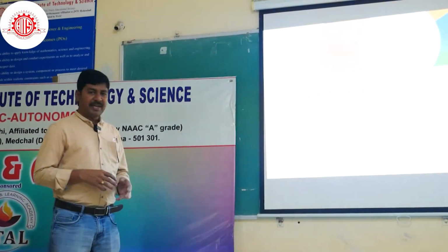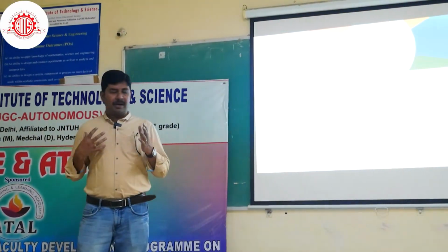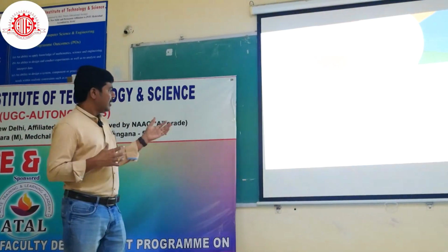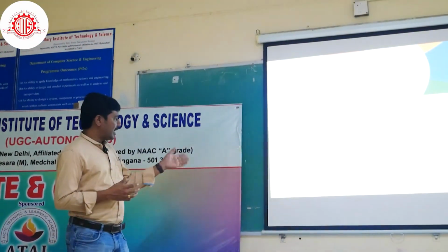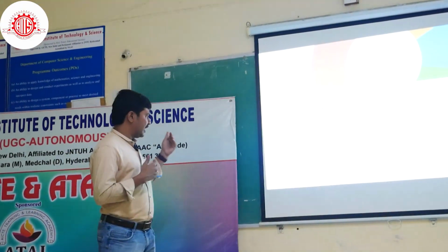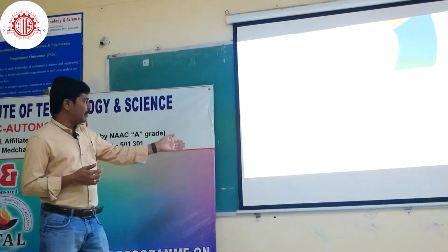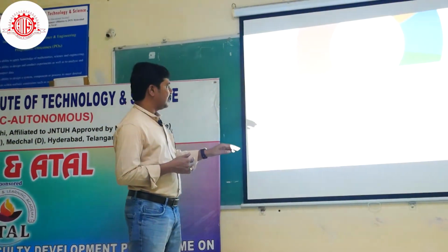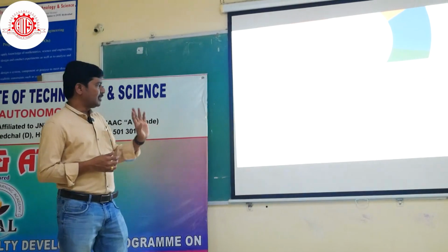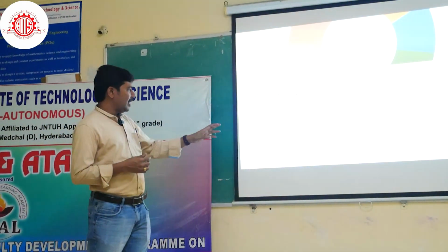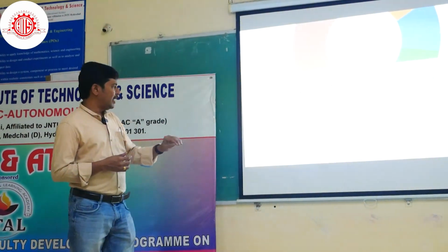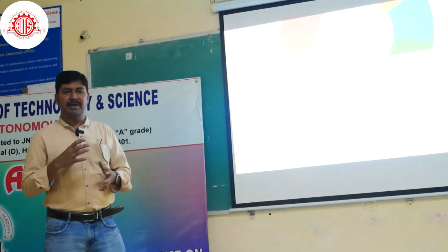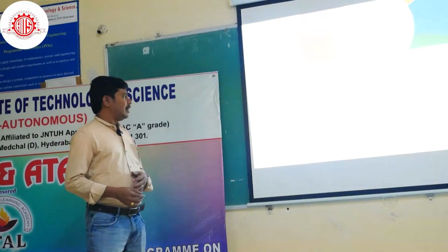You take waste and use temperatures of up to 850 to 1200 degrees centigrade, and use this thermal process to generate energy. The second one is the biological process, where we have bacterial decomposition without oxidation. This will generate mechanical biological treatment, combined sorting and biological processing. So these are the two methods by which waste can be converted into energy.